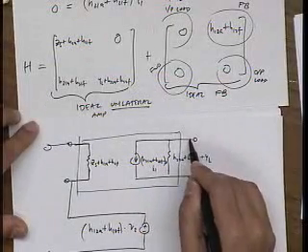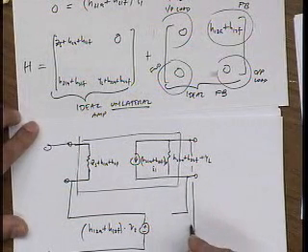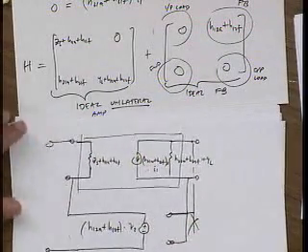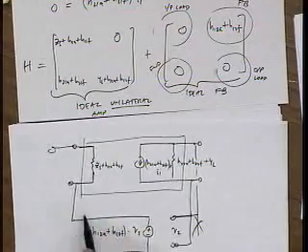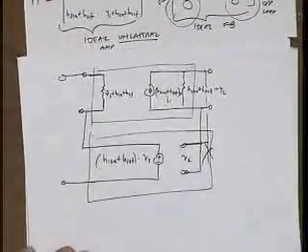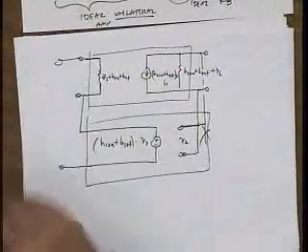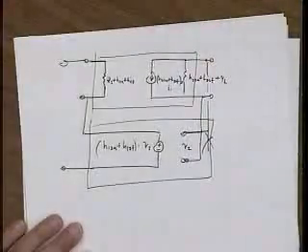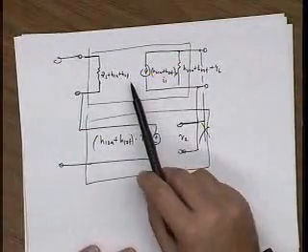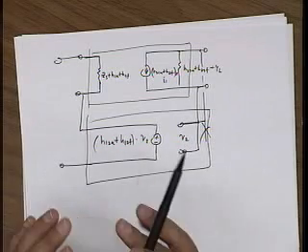And then the output is simply just copied over here without any kind of loading. Whoops. Not a very pretty picture, but the results are pretty, right? So apparently, in order to do a calculation with a real amplifier, all I have to do is calculate the H parameters of my feedback structure, lump them into my amplifier, and I'm done.